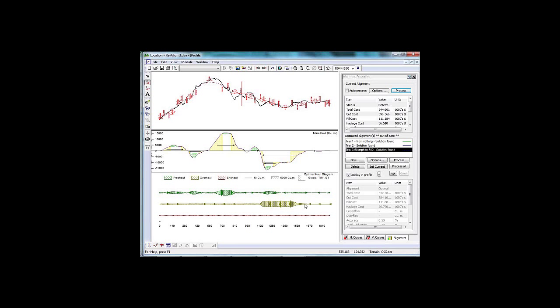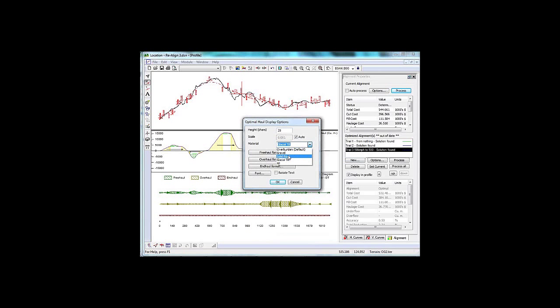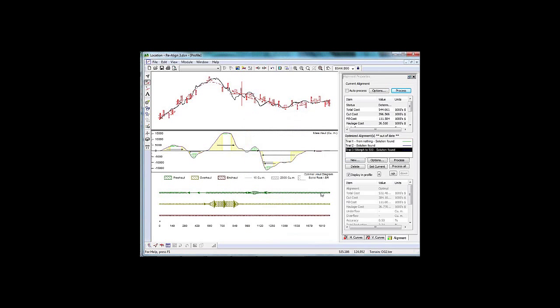What we see here is we're cutting along here, we're moving the material, and then we're filling down here. Now the yellow one is overhaul, so that's movement that's beyond a certain distance. The green one is freehaul. And yeah, so this is another way of displaying the material movement, and it is the information that's being generated by the optimizer. Let's see what the solid rock movement looks like. Okay. So there's only solid rock in this area, and there it is. We got some long movements here, and we got some short movements over there.